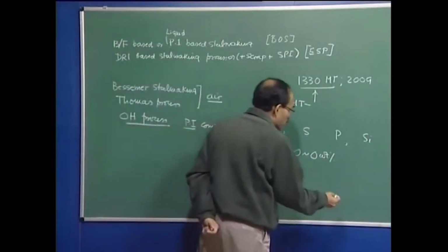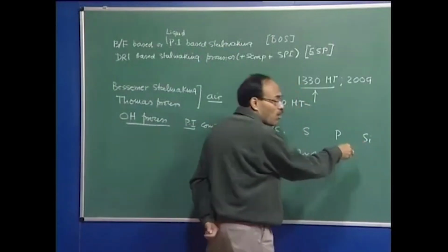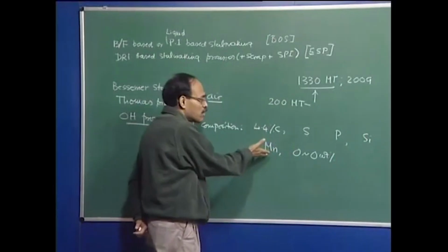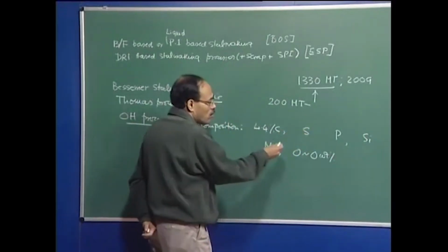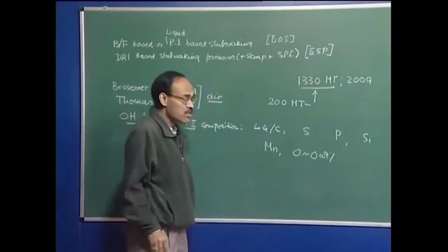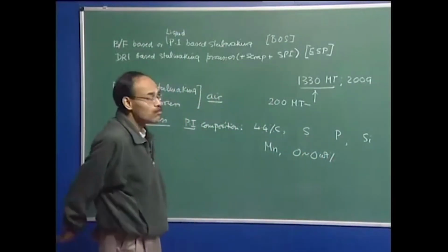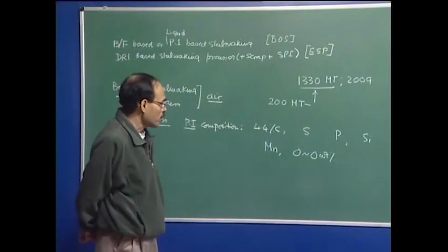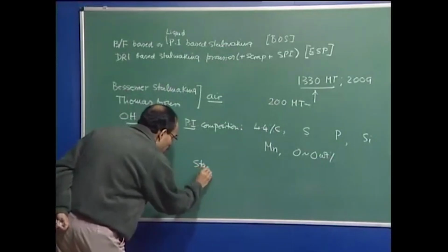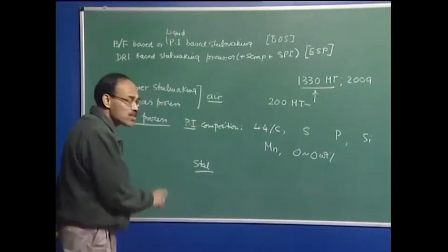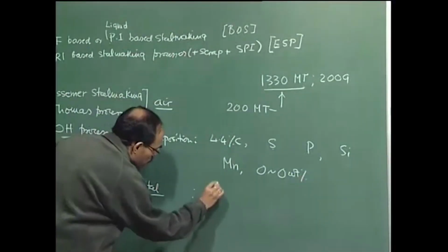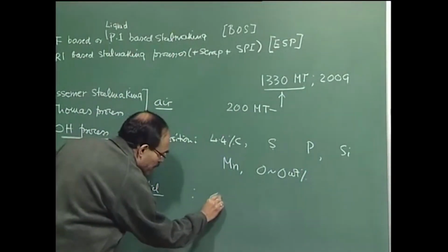For example, silicon could be of the order of 1 weight percent, manganese of the order of 1.5 weight percent, sulfur of the order of 0.15 or 0.12, and in the blast furnace we have no phosphorus removal, so phosphorus could be about 0.15 and so on. Now, when we talk about crude steel, which flows out of primary steel making, we can have carbon less than 0.1 percent.